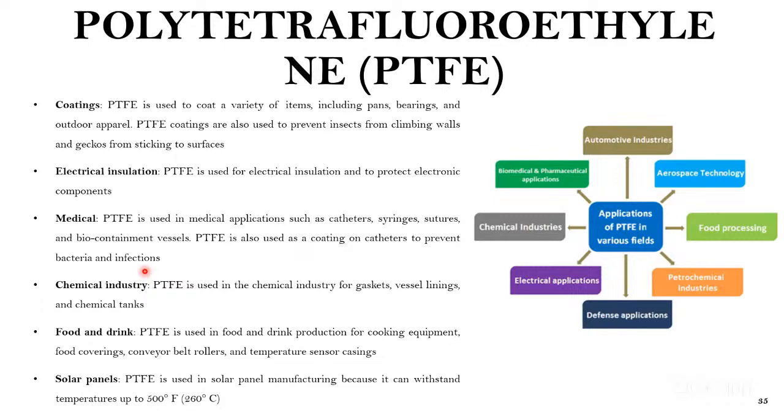Okay, due to their low surface energy, sorry, low surface energy means high contact angle. High contact angle means they are hydrophobic in nature. So due to that property, PTFE is spray coated onto catheters to prevent bacterial or virus infection.